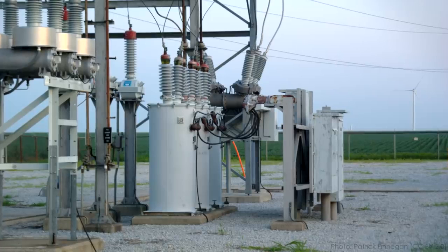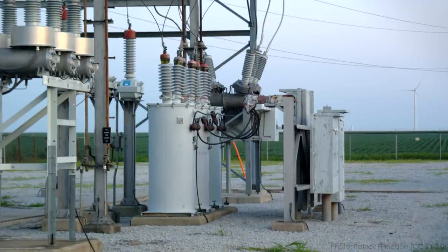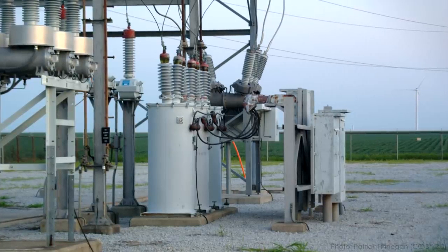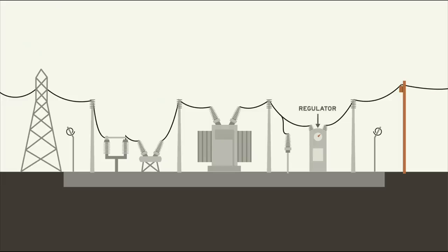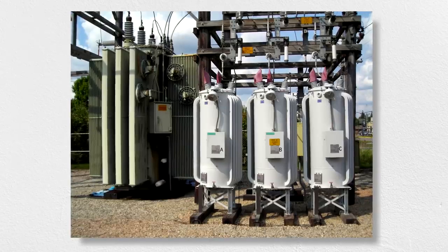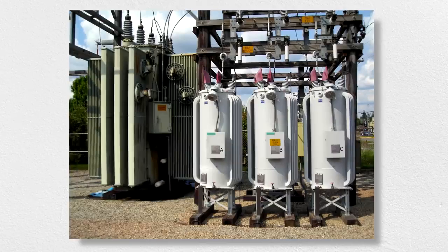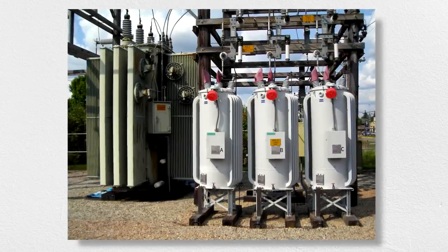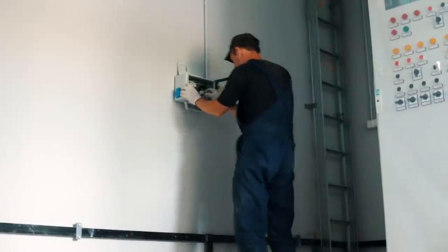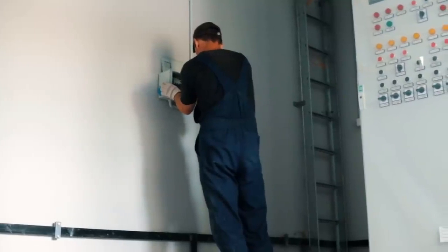Depending on the varying transmission and distribution losses, the voltage on the grid can also swing outside an acceptable range. Regulators are devices with multiple taps that can make small adjustments up or down to the distribution voltage on feeder lines leaving the substation toward customers. If you look closely, you can sometimes see the regulator dial indicating the tap position. All that different equipment requires lots of maintenance.